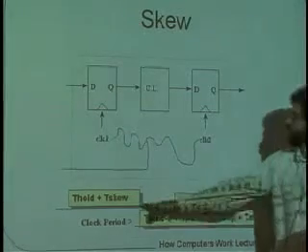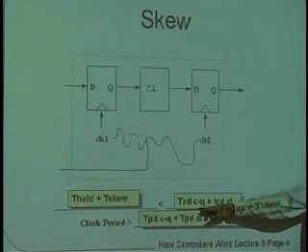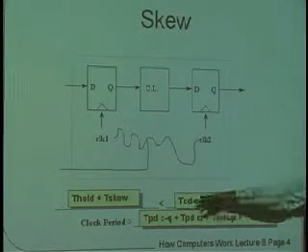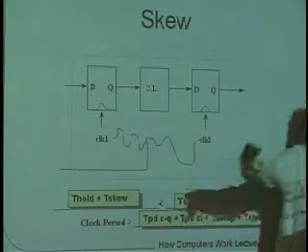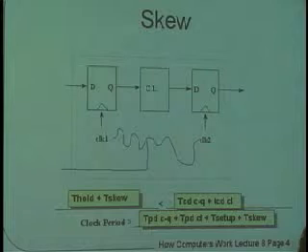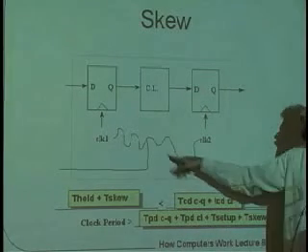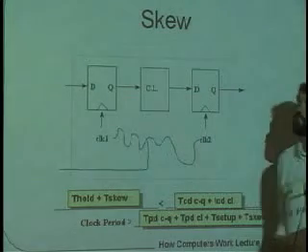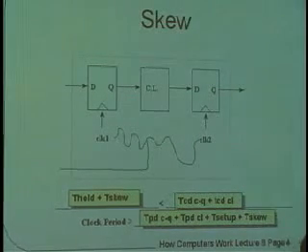And the answer here is that you add the clock skew on the left-hand side, saying that we have to ensure that the contamination delays are greater than a number which is bigger than it used to be because of clock skew. Yeah? What does the squiggly line represent? The squiggly line represents my attempt to draw the fact that this path is a different length than that path. Although, if you looked at it and measured it, it may actually turn out that they're the same length.